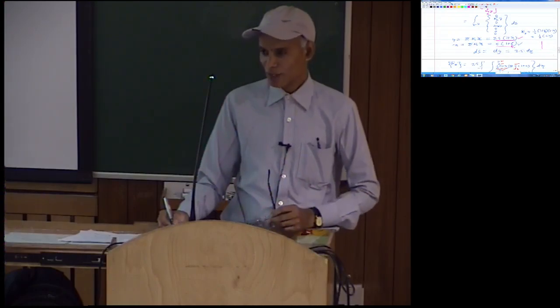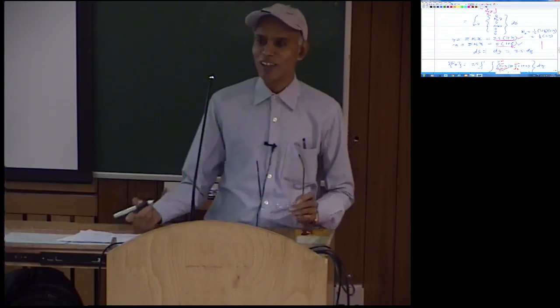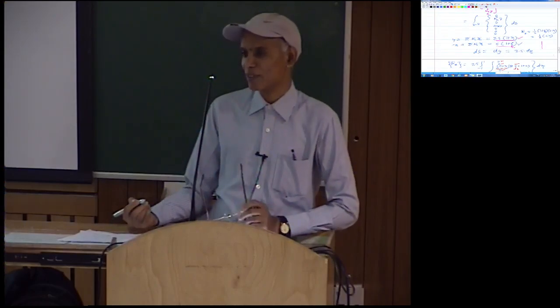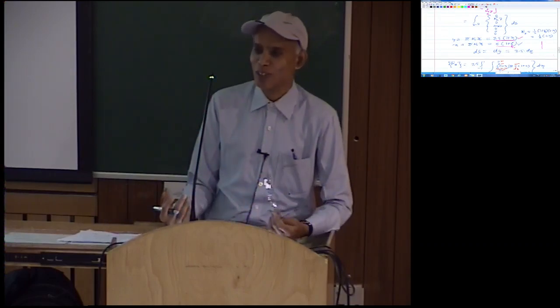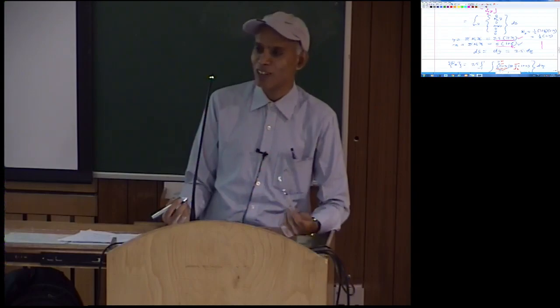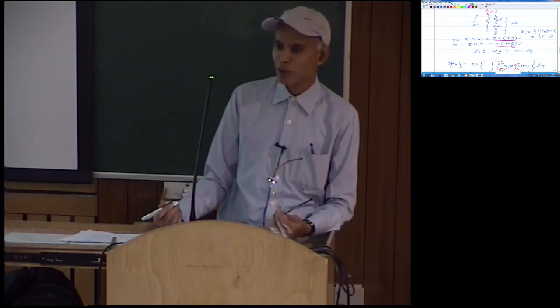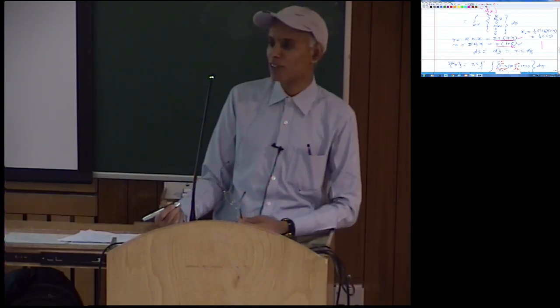Here also it is along one edge, but this is acting on two elements. So that's the only difference. And this is isoparametric formulation, where you have a choice to either use isoparametric formulation or the formulation in the physical quantity space, that is using area coordinates L1, L2, L3.